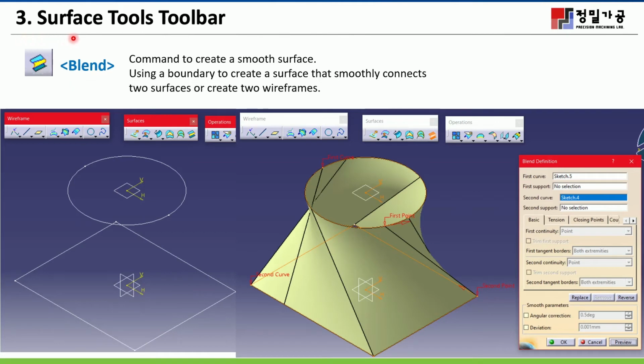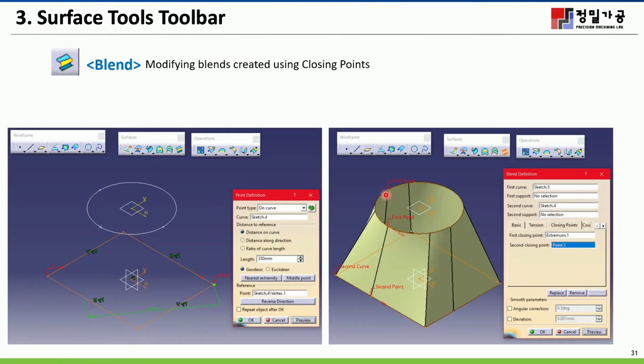So this one is, I think, the last of our class using blend. Maybe if you have two surfaces in here and another surface, you create a surface between them. But this one is an example. I draw a circle and rectangle like a multi-section surface. But I think this one is not a proper example. But anyhow, blend is to create a surface between two surfaces.